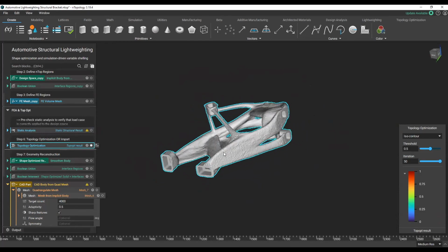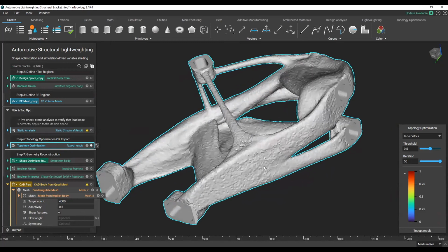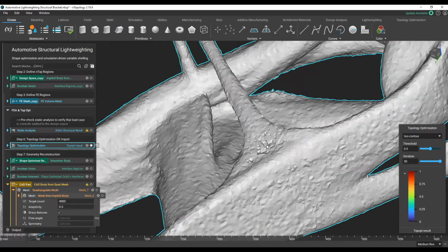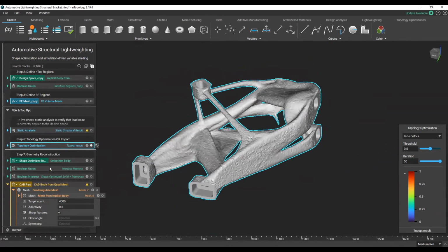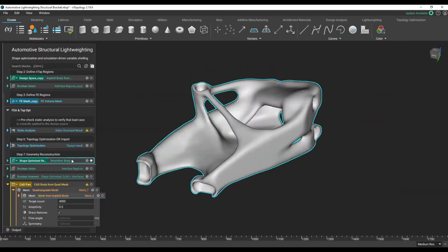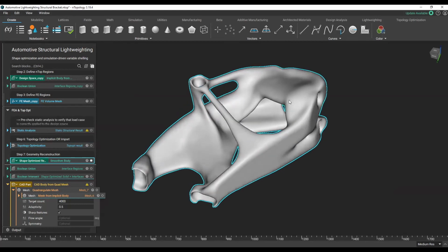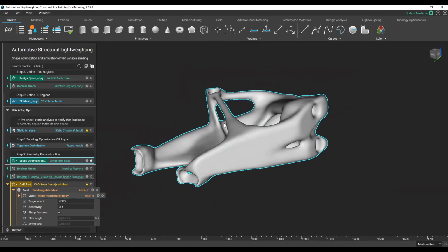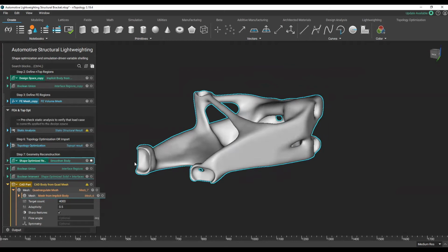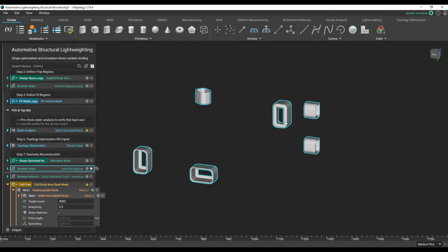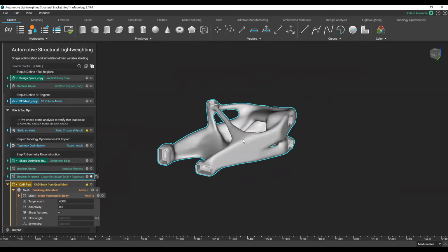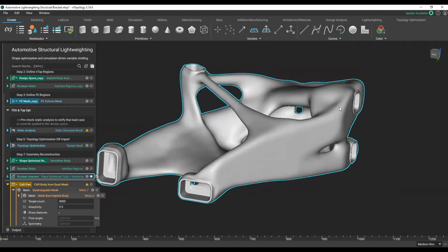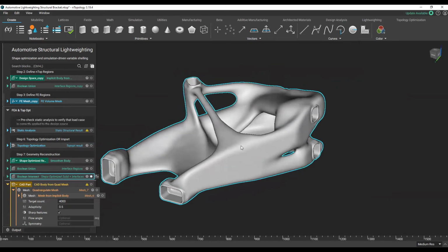In traditional CAD systems, this is where it can get quite complex to remove all of these sharp edges. But in nTopology, we have a smoothen body block, and we can really quickly smoothen out the result to make a nice looking shape, nice faces. We can see that we've lost some of the interface sections here, but with the Boolean that we took earlier of all of these interface sections, we can merge everything back together. So we have some nice edges, nice intersections and interfaces where we want them.